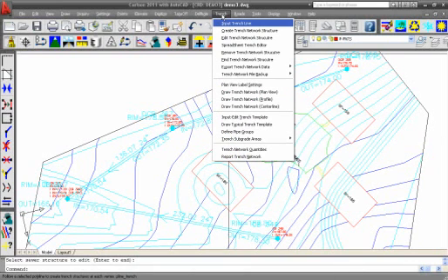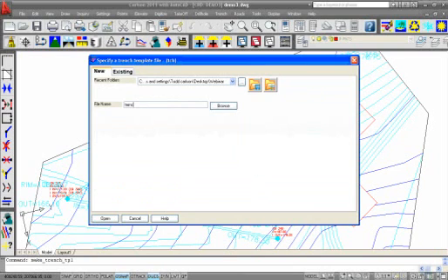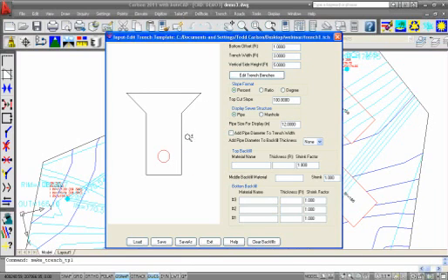Some more things with the trench. If I do, let's see, a trench template now. Input edit trench template. This is something that's changed as well. Okay, so I'm just creating a new template file for the trench, open. All right, these things are the same. Bottom offset 2, trench width 3, vertical side height, let's do 5. Okay, so after 5 feet, we'll start sloping back in to tie into the surface.